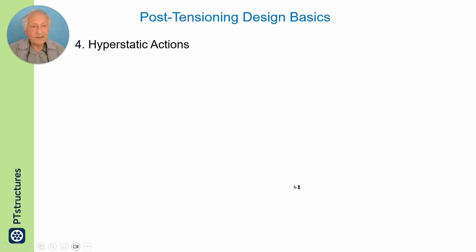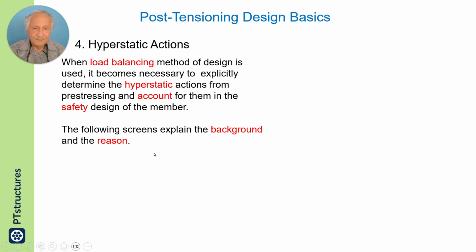Now let us talk a little bit about hyperstatic actions. When load balancing is used, it requires the hyperstatic actions to be extracted and accounted for in the safety consideration of the member.